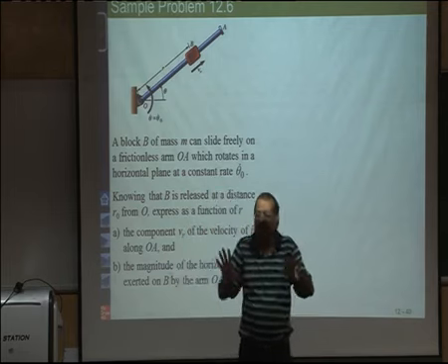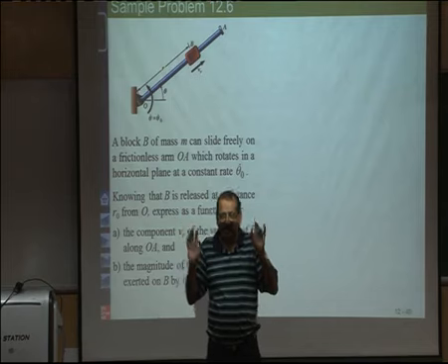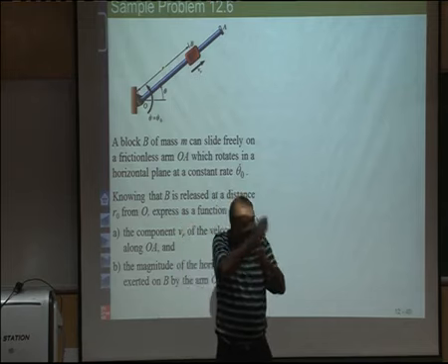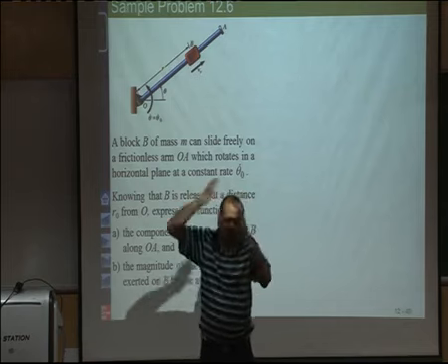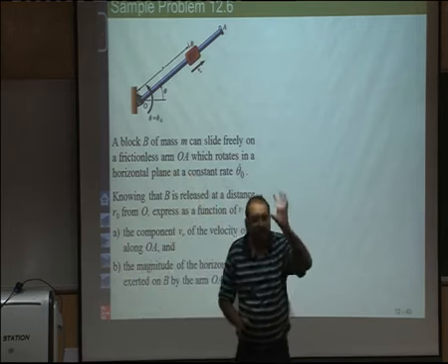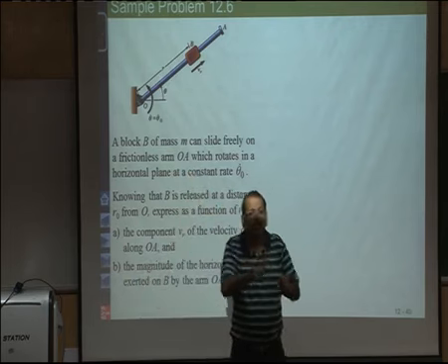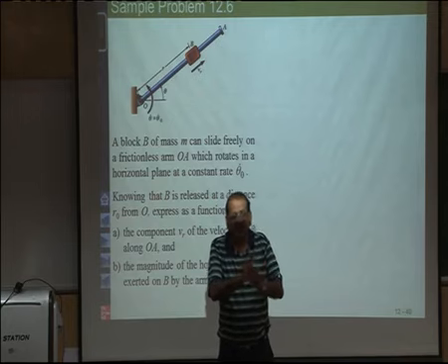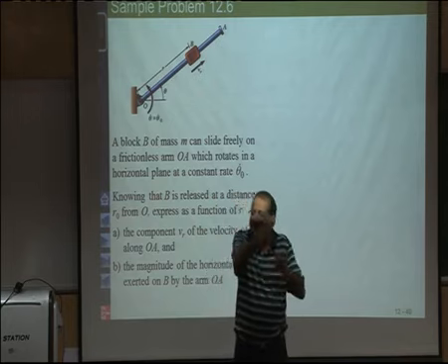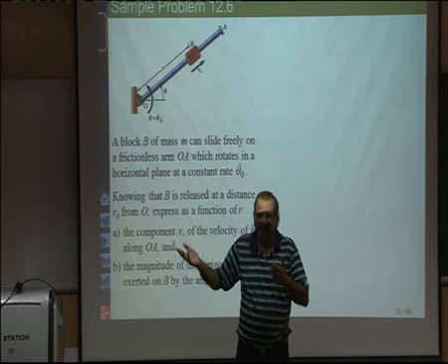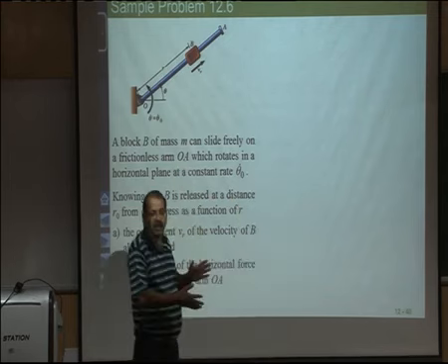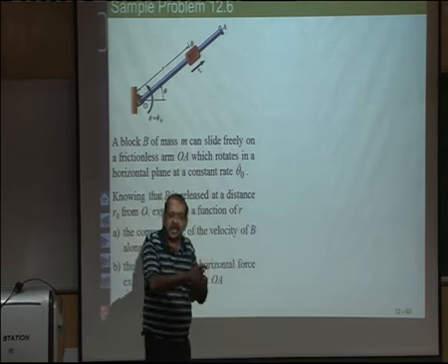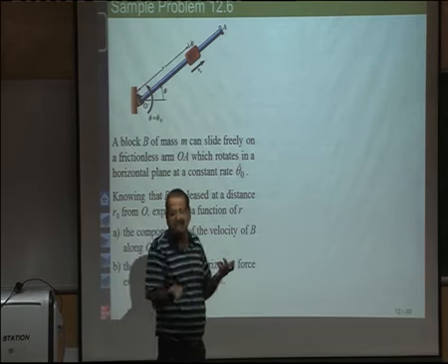So the variables you will be able to solve for will be the same number. If it is being constrained, then a force will come. And this we have seen when we did the free body diagrams. Anything which stops some motion causes a force or a torque. So that is what is happening here. Here we have cut that string. That's the difference between the last problem and this problem. If we have cut the string, that force has gone, but there is an extra acceleration.